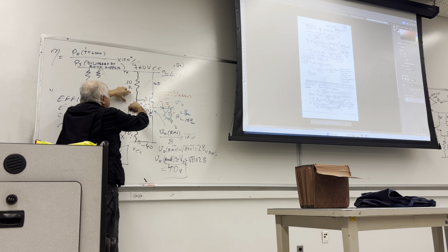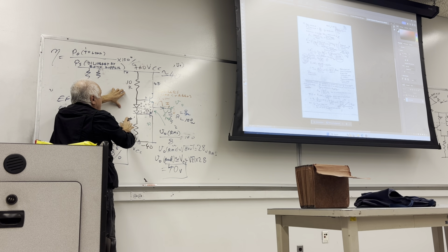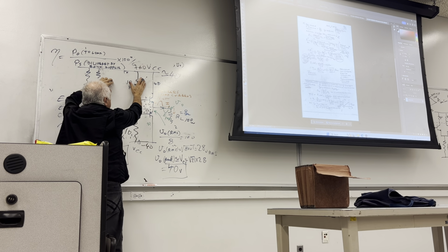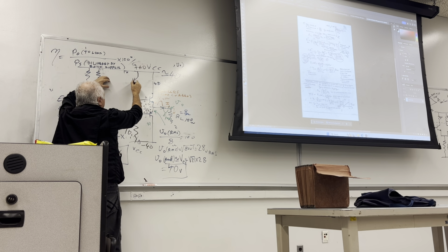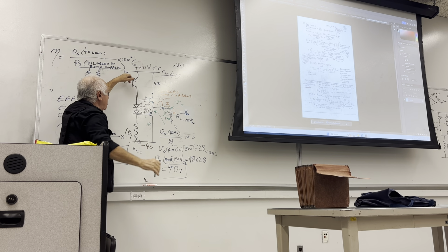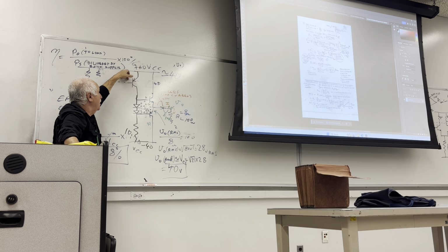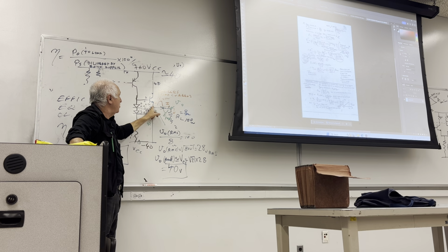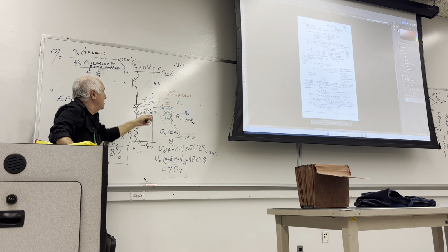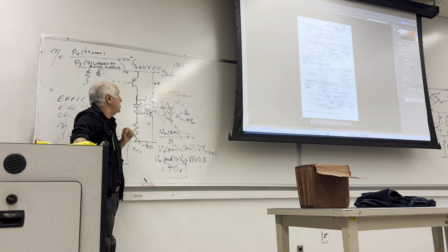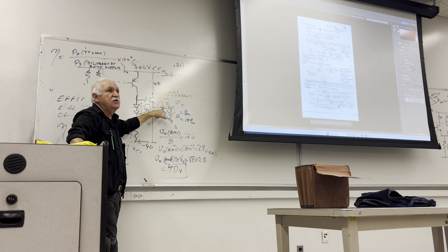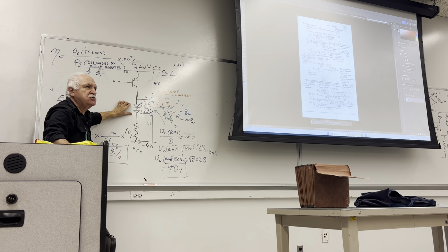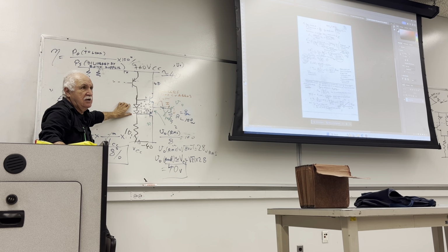And then the amplifier, instead of using that one, it will feed this section with the PNP to the differential amplifier, etc. So that last stage will feed this point up and down, and those two diodes will compensate with the 0.7 volt drop that is needed between base and emitter in order to avoid that crossover distortion. So this eliminates the crossover distortion greatly.